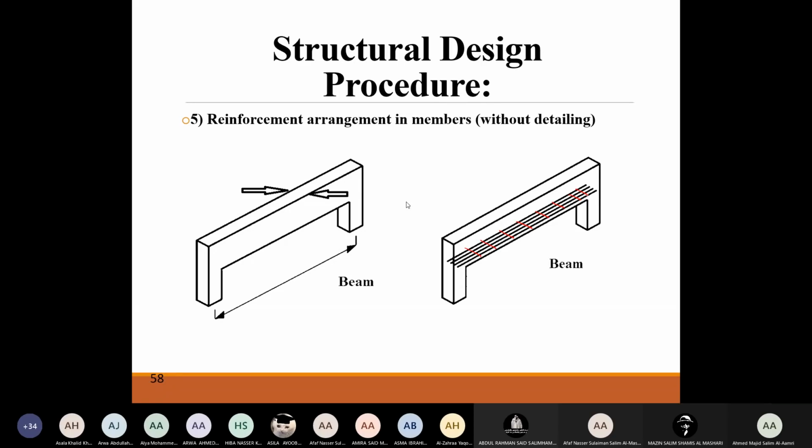That's why in a one-way slab, we only calculate one moment and the other side is taken as a minimum. In a two-way slab, both of them are major, both having high value moments. So you need to calculate the reinforcement for both sides. Are we okay?